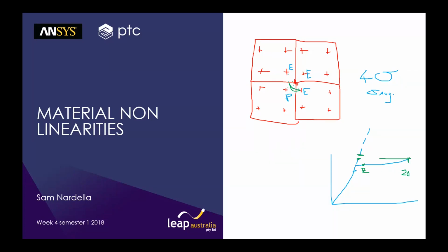Where you have a very sharp transition to plasticity, this becomes even more pronounced if all of these stress states are elastic and they're all close to yield, so that the elastic stress it extrapolates to, all of them are above yield. So that means that your average is going to be greater than yield.